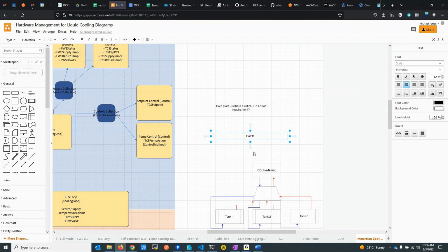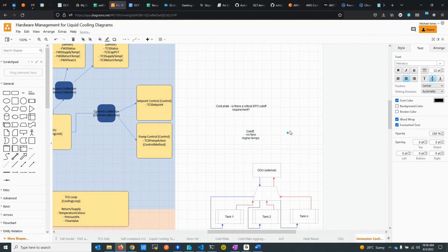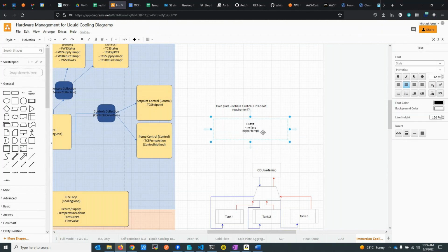Not only that, but the margin you have with those higher temperatures is less. You will see a spike or an increase in temperature that maybe the server itself, with the BMC and the cutoff algorithms already implemented for air in the BMC, is not enough to safely shut down that server. So this is why most of the time it's safer to operate at a PDU level.